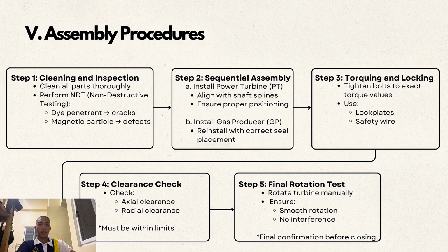The final steps involve sealing the unit. Install the turbine outer shield and the exhaust collector support. Mate the turbine sections to the compressor gearbox. Carefully align the spline drives. Install the V-band clamps. Ensure the T-bolts are torqued and safety wired.